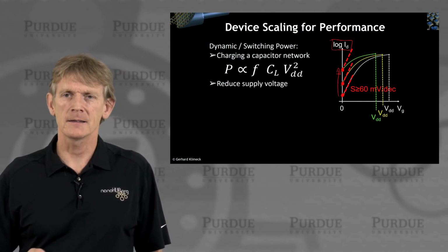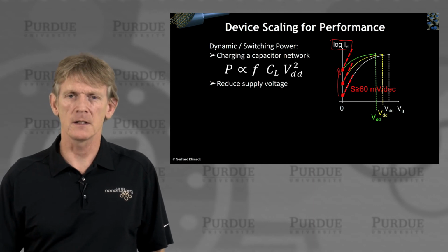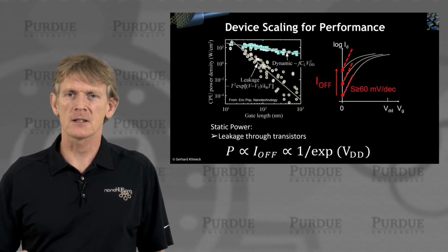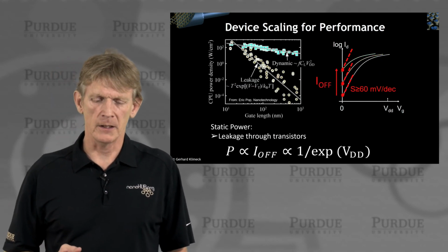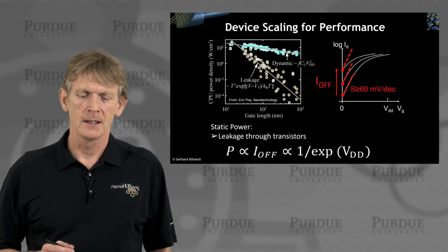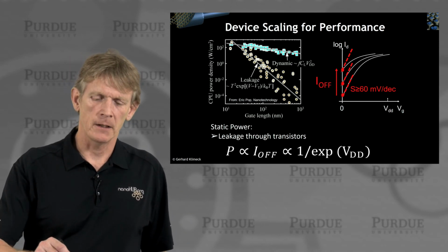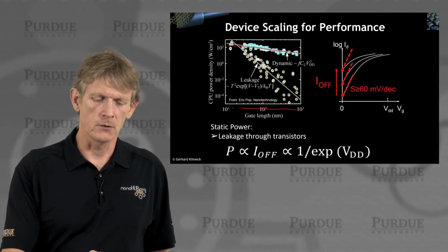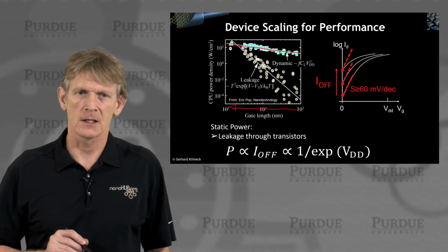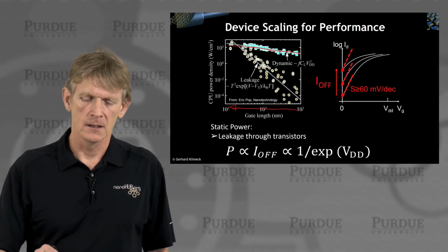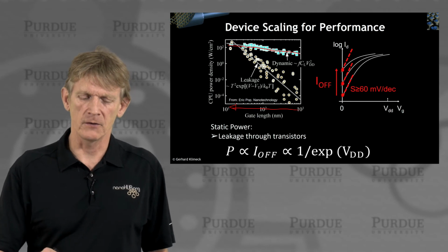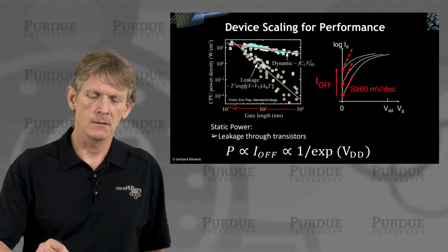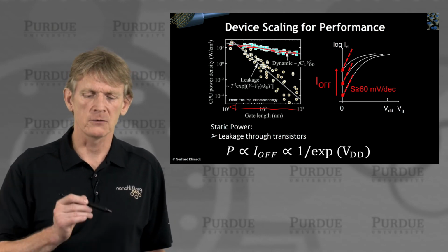All right, so that is what has happened over the years, and you get to this leakage through the transistors. And there's actually data that has been published by Eric Pop quite some years ago, where he is plotting the dynamic power in these transistors over, these are now technology nodes or gate lengths, okay? So think of this as a historical axis going backwards. We got devices that are smaller and smaller, the gate length got smaller and smaller, and the dynamic power has risen moderately.